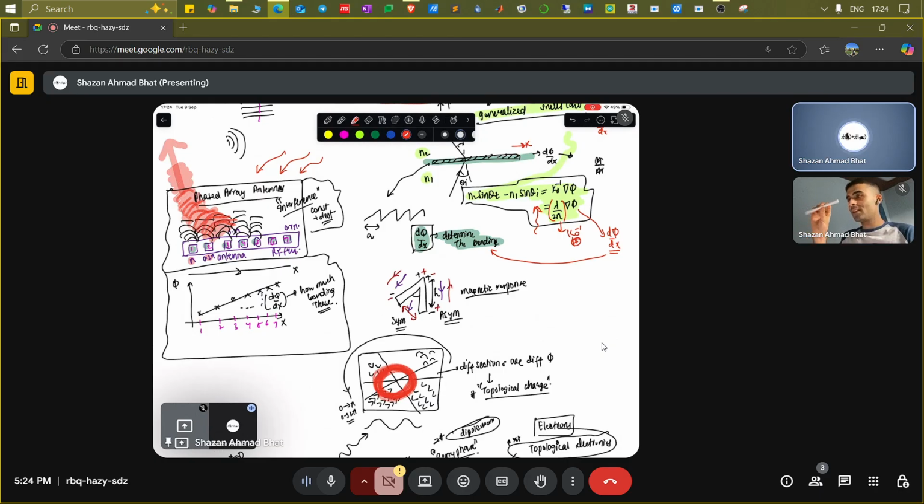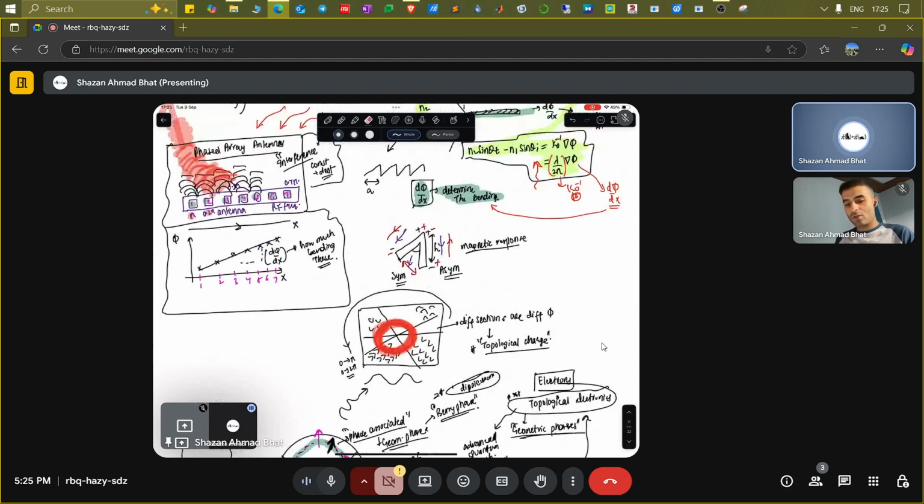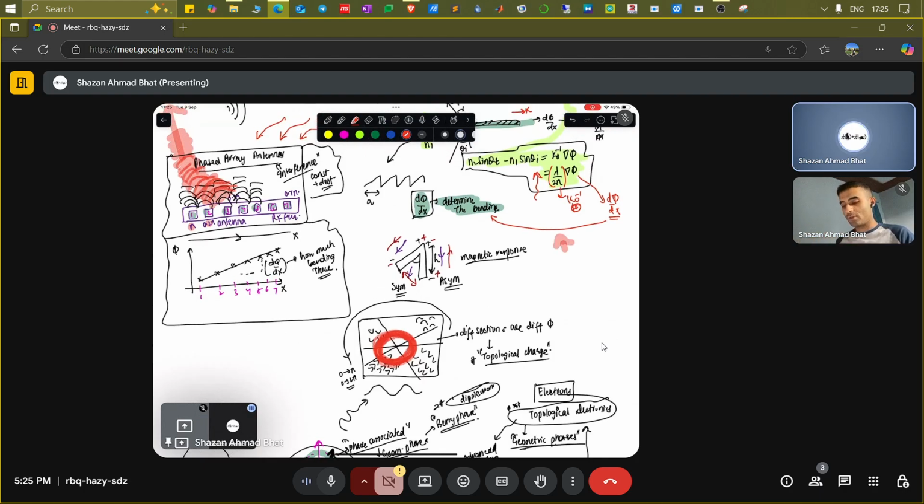Let's say there are certain patches of antennas present on this particular pencil. If I want to throw the wave at this angle, one way to do this is that I can just turn the antenna like this. But here what we are talking about, the antenna looks like this, the antenna is just like this. What you are doing internally is that the emitted phases of the electromagnetic waves are different. That is automatically going to transmit the electromagnetic wave in the direction I showed earlier. So that is the fascinating thing about this particular concept. It is almost a similar concept, but here you are giving a spatial type of phase because of the varying thickness.